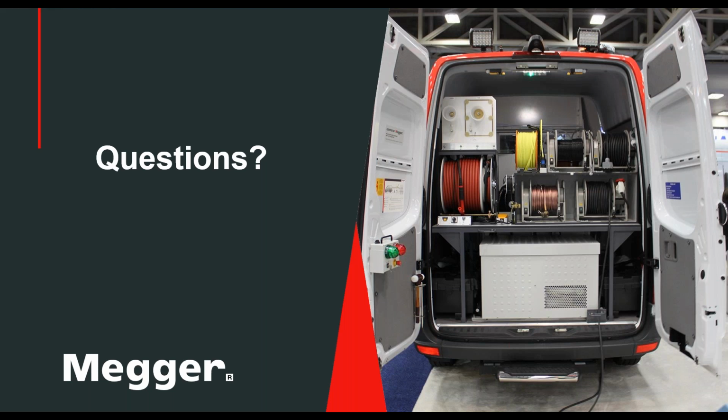It was already there. So from a practical point of view, as long as you keep your voltage under control and you're not excessive in the amount of time, you're not out there thumping on a cable for half a day because you're not using the right technique, you're not really too concerned about damaging the cable itself with the thumper.